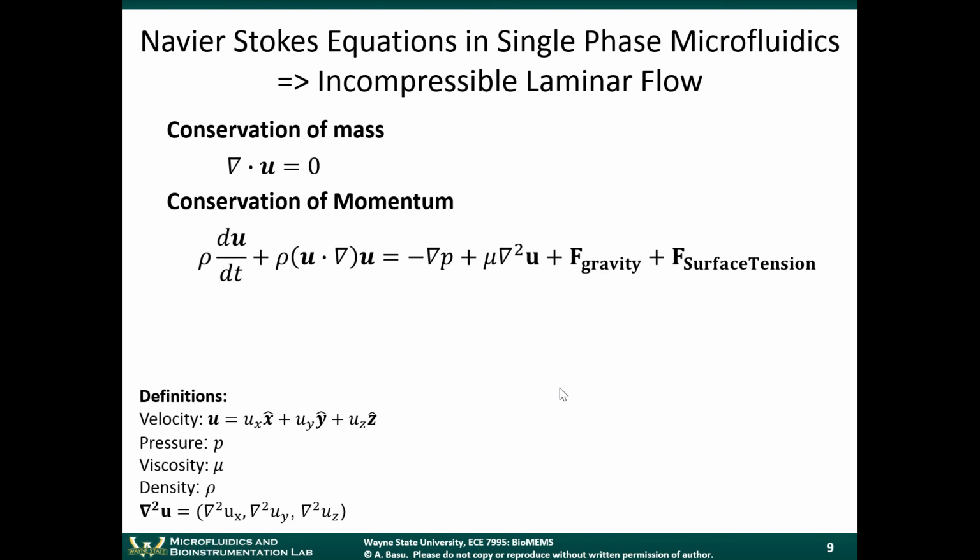So, getting to the Navier-Stokes equations for single-phase microfluidics. We're talking about the flow of a single liquid through a microchannel. We assume that the fluid is Newtonian, and we also assume that it's a liquid, so it's incompressible.